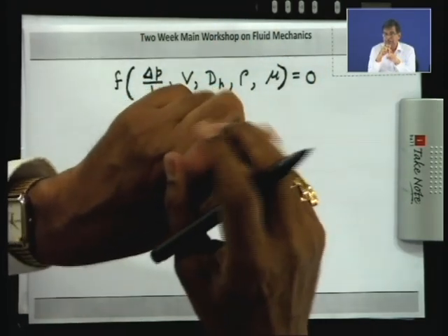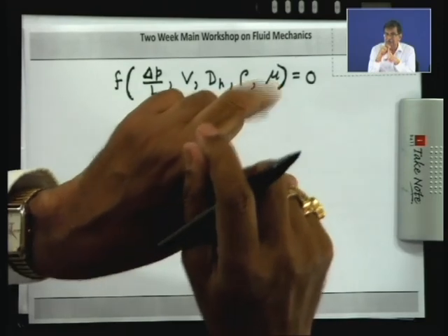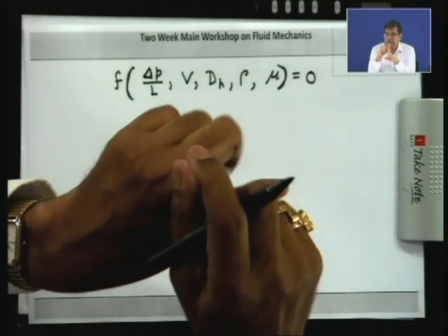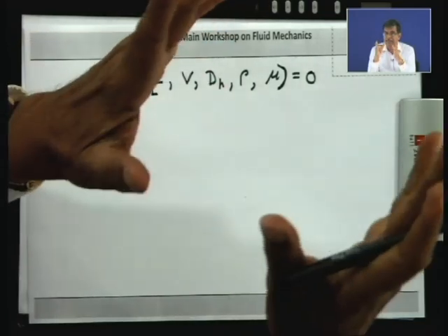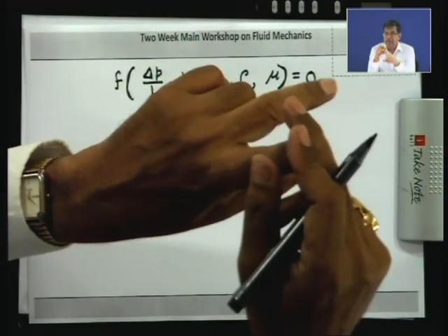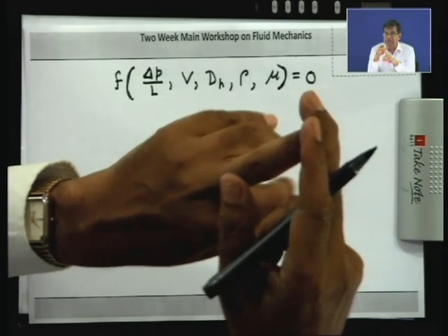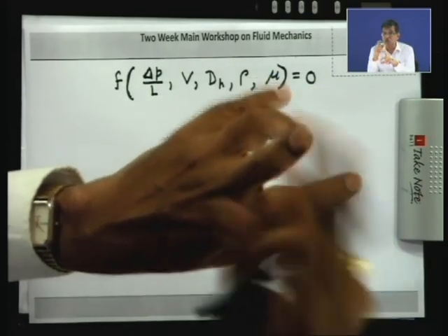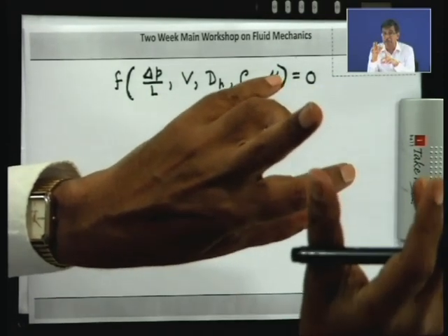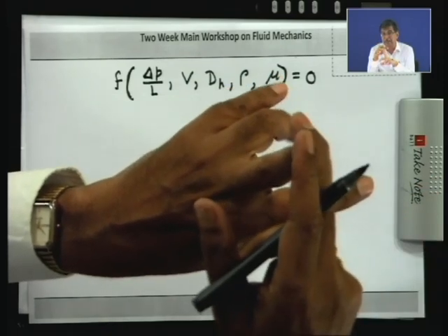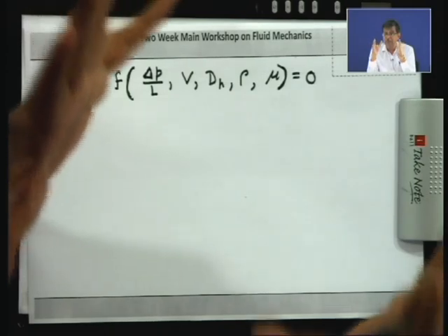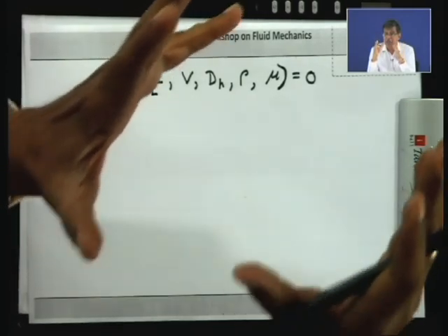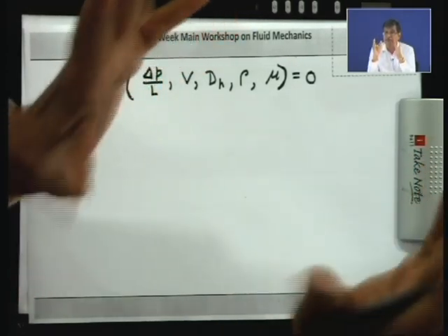While applying the pi theorem, two things have to be remembered. The number of repeating variables has to equal the number of fundamental dimensions, and any arbitrary variables can be taken. Second, the repeating variables should not contain the output or performance parameter of the system. Third, all the repeating variables must collectively contain all the fundamental dimensions.